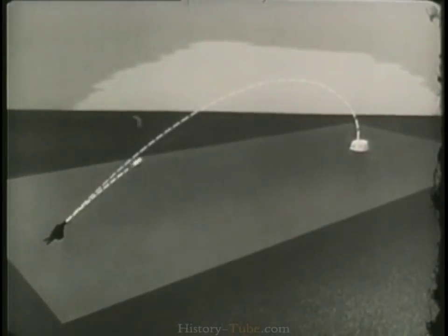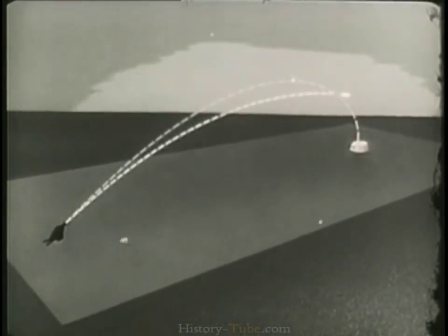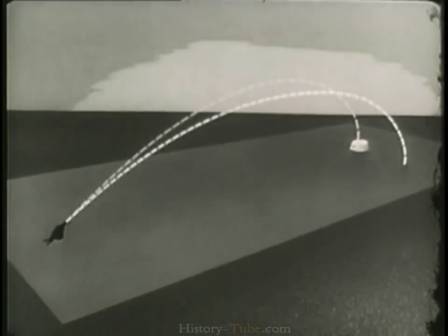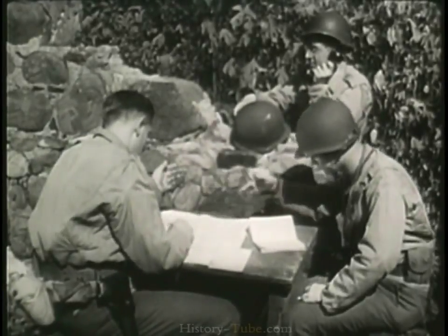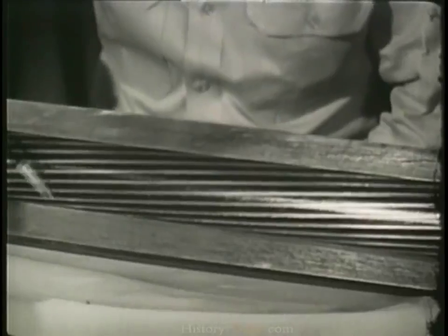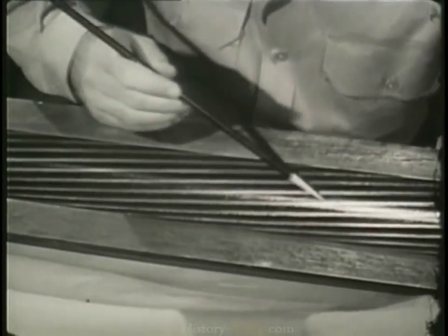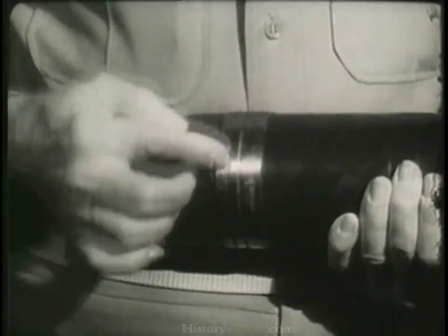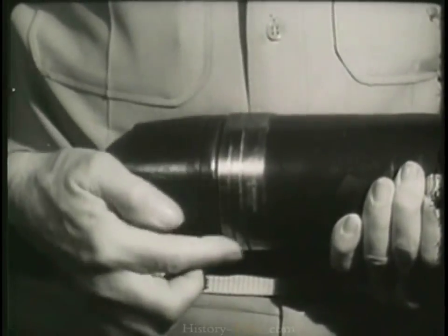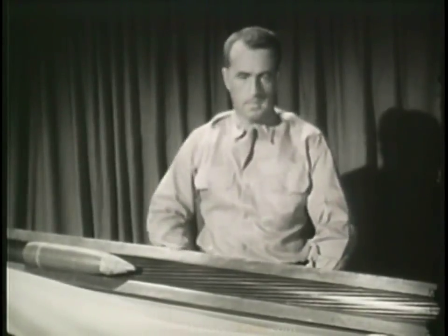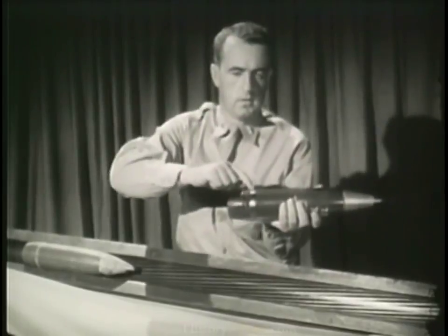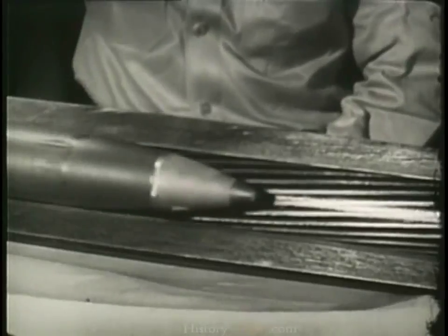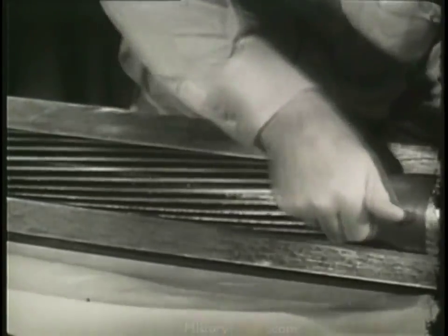This, however, causes the projectile to swerve from a straight course, drifting to one side according to the direction of the spin. That isn't as bad as it might seem because we know it's going to happen, and we allow for the drift in aiming. To get the required spin, spiral grooves are cut in the bore of the gun and a soft rotating band put around the projectile. The band engages the grooves and the projectile rotates, or spins.